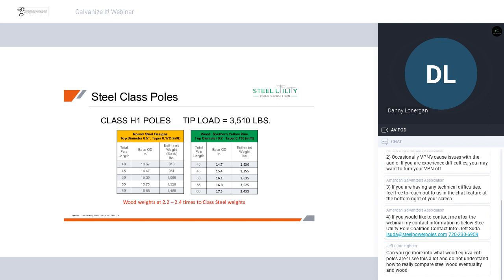That comment will really take me to software, but I forgot I dropped in one slide yesterday. So before we get over to the software, my comment on deflection is really best captured in software, but I want to just touch on weight. There's often a misconception that steel poles weigh more than wood poles, and factually, it's the exact opposite. Steel poles are typically less than wood poles, and a good rule of thumb is half the weight.